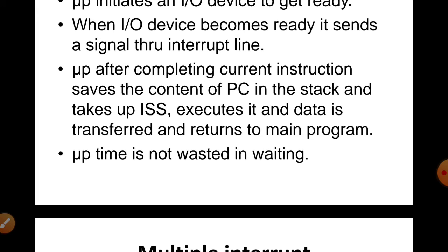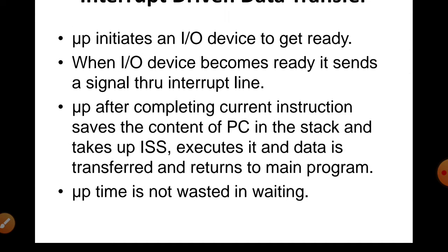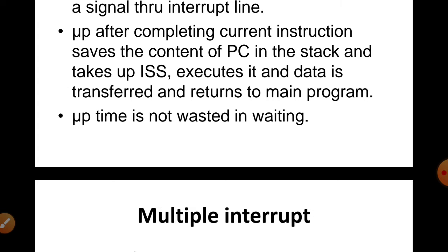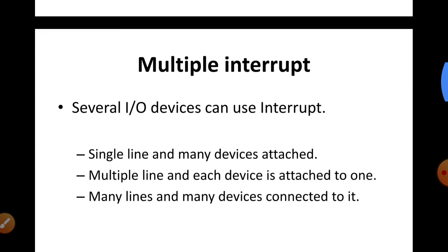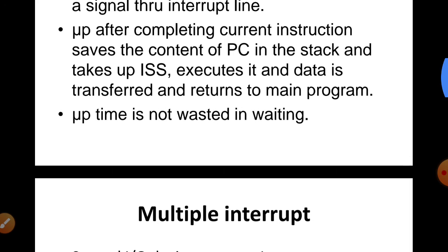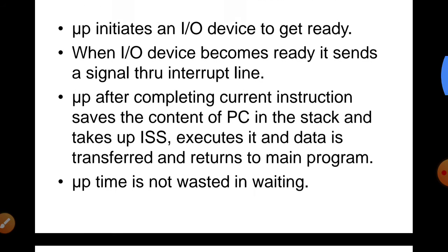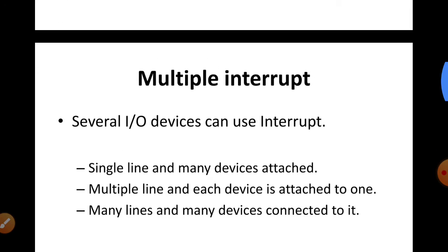The interrupt service subroutine is already made by the manufacturer, and it is stored at a certain memory location. Whenever the request has been granted by the processor, it stops its normal execution and executes the service subroutine related to that particular line through which the peripheral has interrupted. This is different from the polling process, in which the microprocessor's time is wasted while it keeps checking whether the device is ready to transfer data or not. In this case the microprocessor is not wasting its time; it is doing its job, and whenever it receives an interrupt, it handles that particular peripheral device.